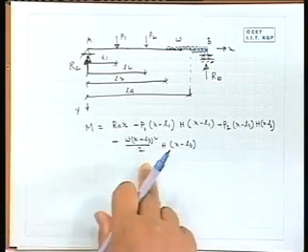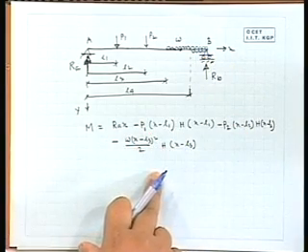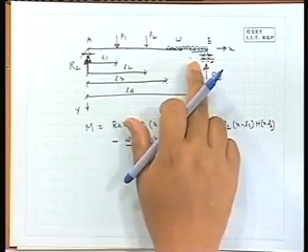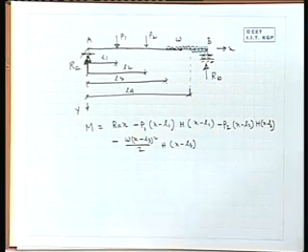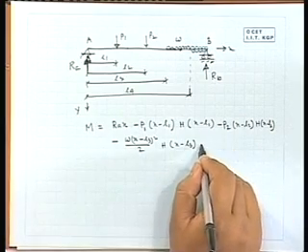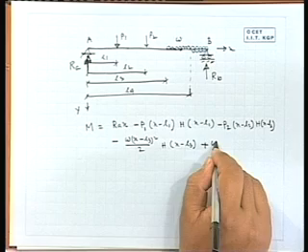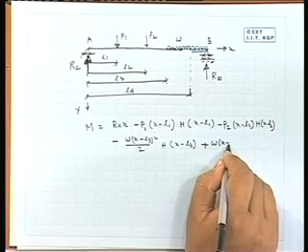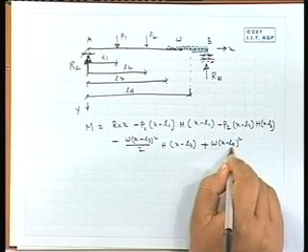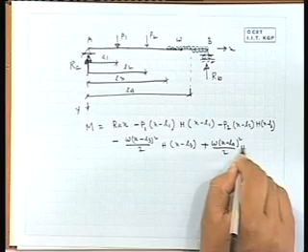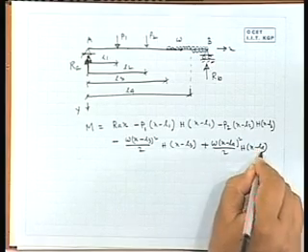So, the upper one can be tackled by the equation whatever we have written, and the lower part is the correcting force. For that we have to add another term, and that will be in a reverse manner, will be plus. So, it will be omega into X minus L4 square divided by 2 times H of X minus L4. Right. So, this is one of the very tricky ideas.